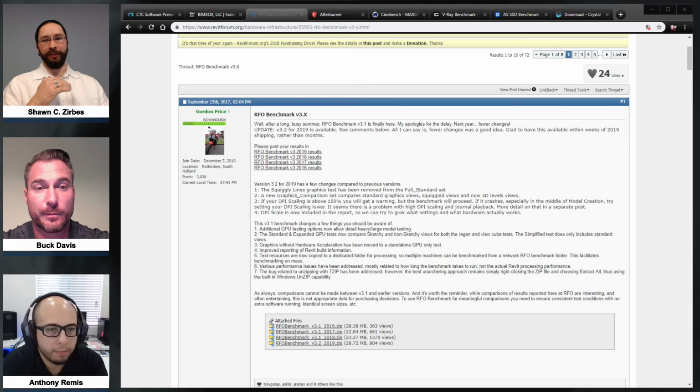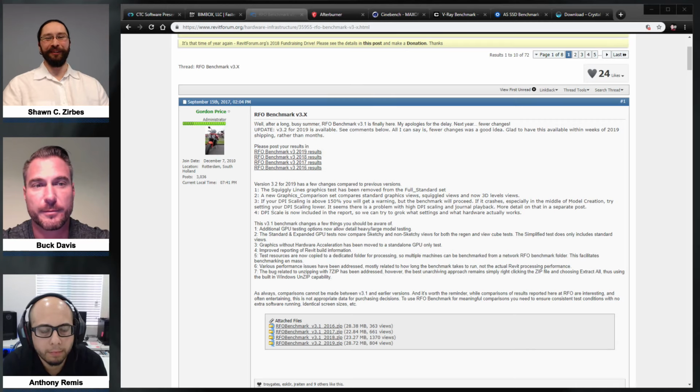I would try to get your system as clean as possible, like restart, do a fresh start, just run it. Don't open up email, don't have peripheral stuff running, close all that Autodesk Communicator garbage, whatever you can do to free up some resources. And then also, I would personally have Task Manager open just so I can see what's going on. And if I'm seeing everything just spike out and then I get that message, that would be a pretty clear indicator. So just some quick troubleshooting on that front.